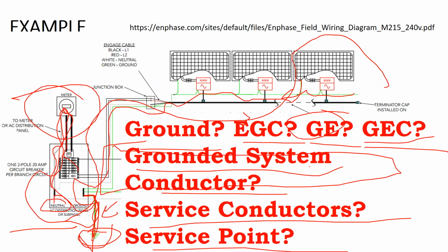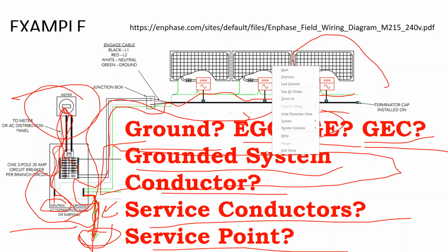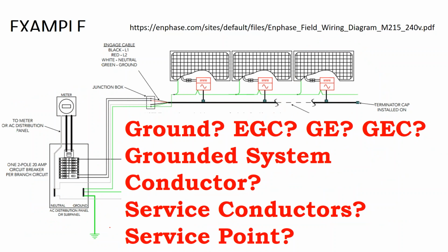There are also issues where, if you're required in an off-grid system or a new construction system to install this ground, even though you put in a ground rod, you might not get the right amount of resistance to ground. Your ground is supposed to be functioning to carry current to ground, but it doesn't have the resistance there. So we get this all the time in Mississippi.